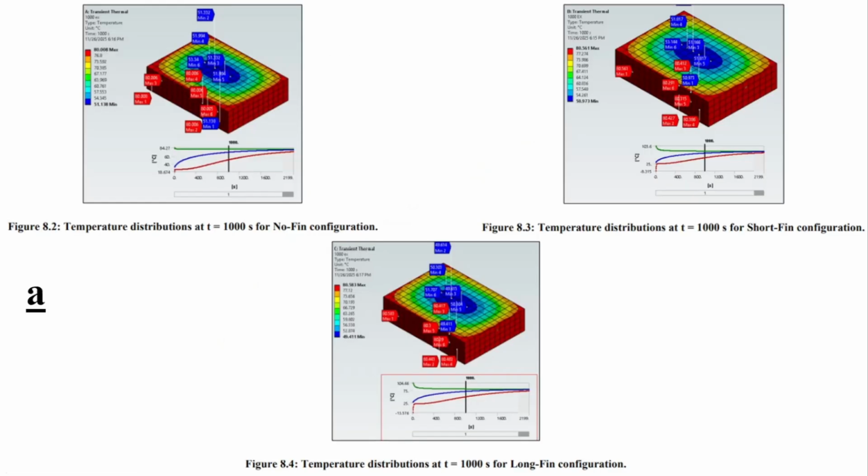Now here we also have a couple of examples related to the results. We can see, not heat flux, but the temperature behavior results. This is the way the procedure was done: it was set up to 1,000 seconds, we evaluated the local minimum and maximum for the temperature behavior, and then that data and the averages, minimum and maximum, were put into the Excel sheet, extracted from the Ansys Workbench, and then we proceeded to download the performance calculation metrics. You can see here the one for the no fins configuration, the short fins configuration, and the long fin configuration.